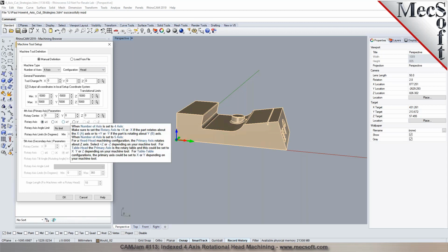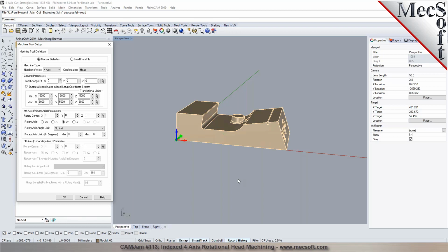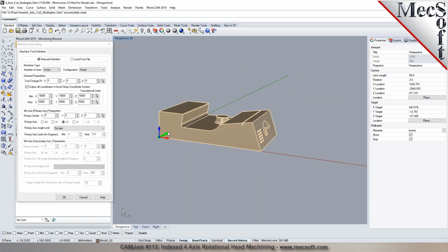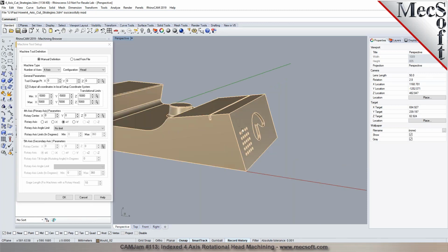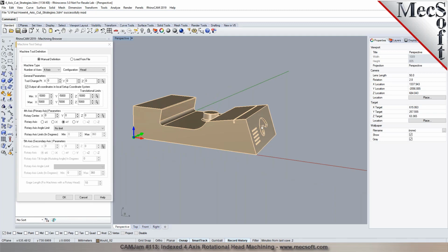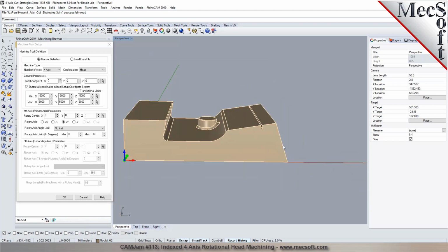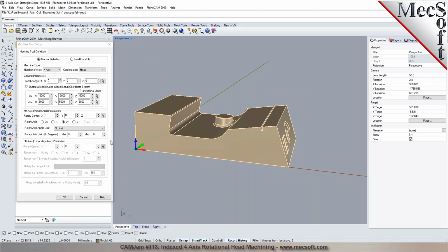I understand that. The rotary axis is going to be defined about the y-axis based on how your machine tool is built. Yes. So that would be plus Y, or it could be minus Y, depending on how the rotations are handled. The plus and minus is determined by the direction of rotation. If you select plus Y, you point your thumb in the direction of this arrow, the rotational axis. As you roll your wrist towards you, that'll output a positive angle. So if the tool is normal to this face, you would see a positive angle, like a B-axis angle being output. And if the tool is normal to the slot, you might get a negative angle because you're rotating in that direction. So the positive and negative depend on how your controls are set up on the machine; you can pick Y positive or Y negative. Okay, I'll have to check that once the machine arrives. Yeah. We basically output based on the right-hand thumb rule here.